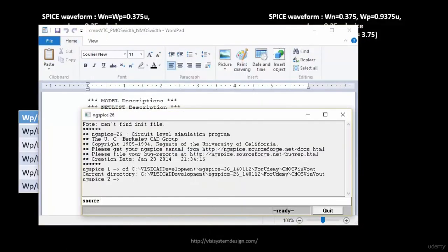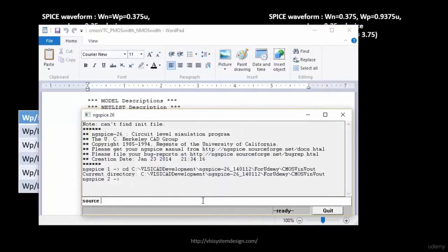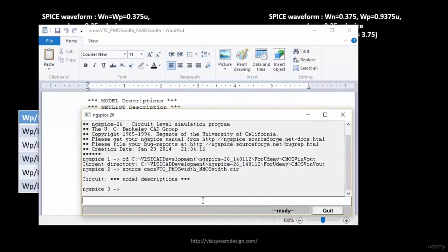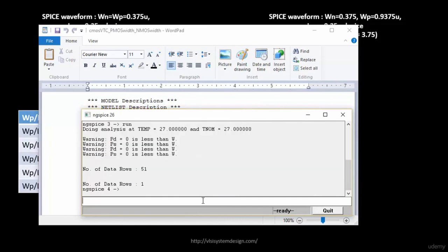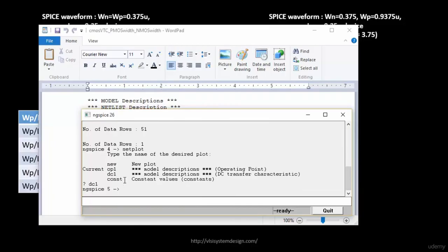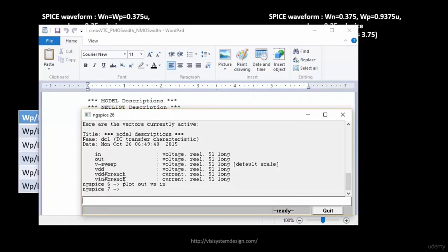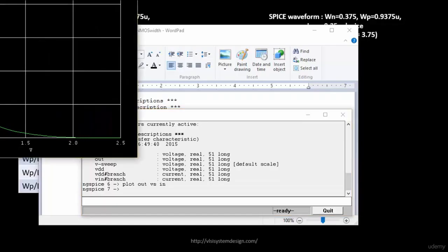The reason they are turned on is because their gate voltage is very much above the threshold region. So this is the case where your Vin is equal to Vout. When you say Vin is equal to Vout, your gate voltage is equal to your drain voltage, which means VGS is much greater than your threshold voltage. So these are the conditions: your VGS is equal to VDS.